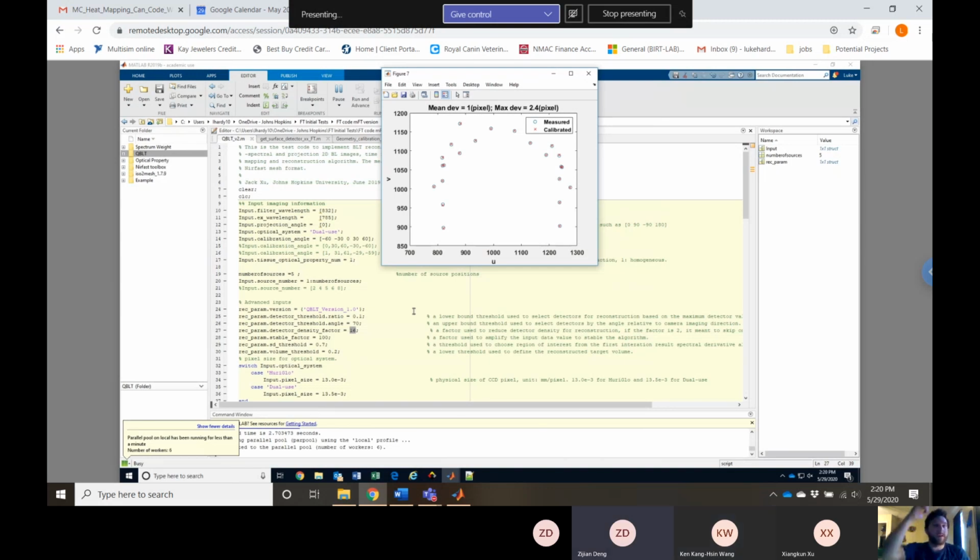Basically, you're rotated 90 degrees from near view when you just import it automatically to NIRFAST. You need to remember to do a rotation transform on the Kang-Hsin CT data when it's imported into NIRFAST, which I will show you here in a minute.